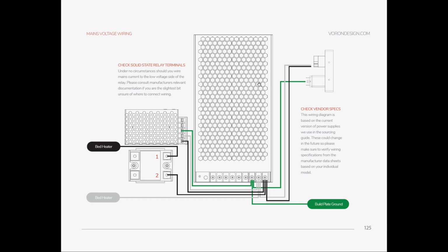Then after that, run your main wire for the 24-volt power supply. Again, after running your wire, plug your cable to the power skirt, and with your multimeter check the voltage in the 24-volt output. If you are getting 24 volts output, then unplug your cable and do the second one. Repeat this until the devices, the components, are finished.